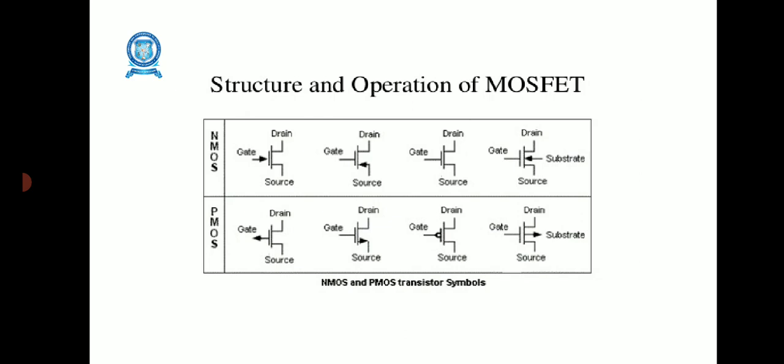While we are discussing this type of transistor, which is the metal oxide semiconductor field effect transistor, these transistors are a sandwich consisting of a semiconductor layer, usually a slice or wafer, or it can be a crystal, and a layer of silicon dioxide. You can see the structure of MOSFET. Here this MOSFET contains three layers. One is the metal gate electrode, next is the insulating oxide layer, and next is the p-type semiconductor.